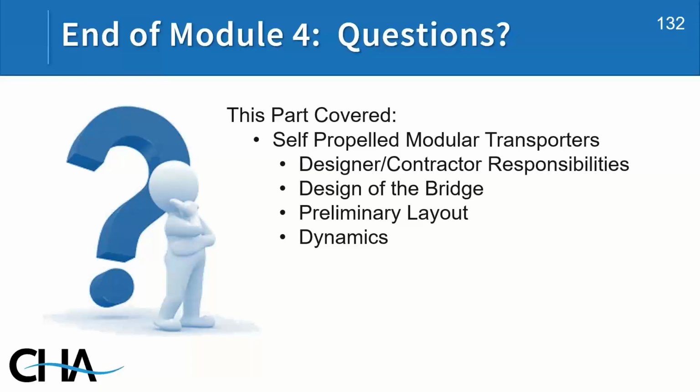And that's within the range of what the heavy lift contractors can design for. So the dynamic guidelines give you reasonable answers that are much better than picking a number out of thin air. And they're based on the actual stiffness of the false work, which is important. Stiff false work will behave differently than flexible false work. And it gives reasonable numbers that can be built.